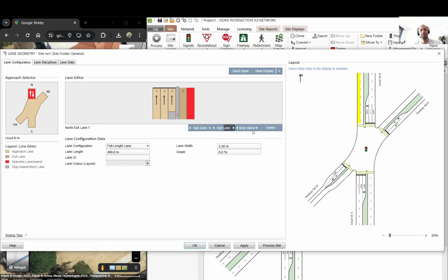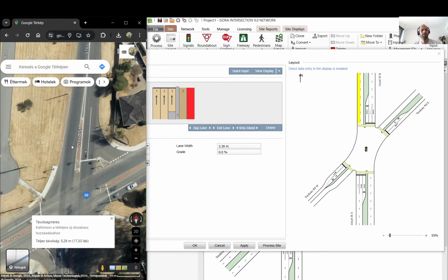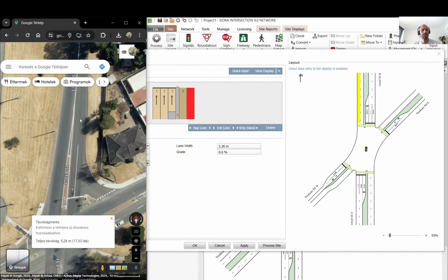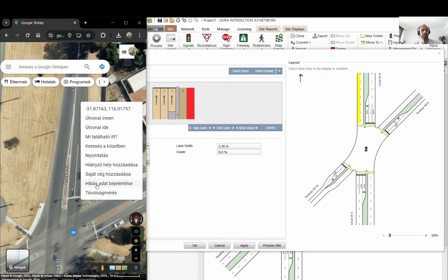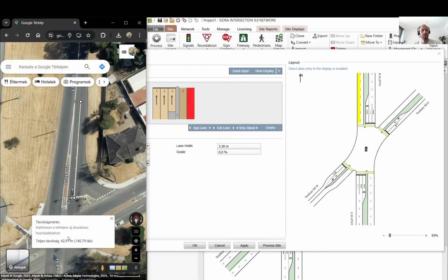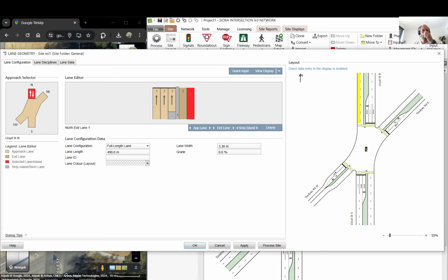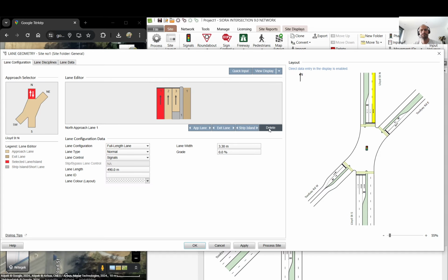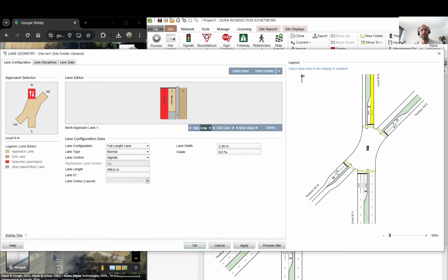And so this is going to be more interesting. So if you look at here, it's a single exit and a short entry, and the 2-lane section is probably starting somewhere here. So it is 43 meters. I think it's 45, maybe it's a bit more realistic, like that. And the short lane is 45. You can round it to the nearest fives. You don't need to be that accurate. And you can see it also shows here.